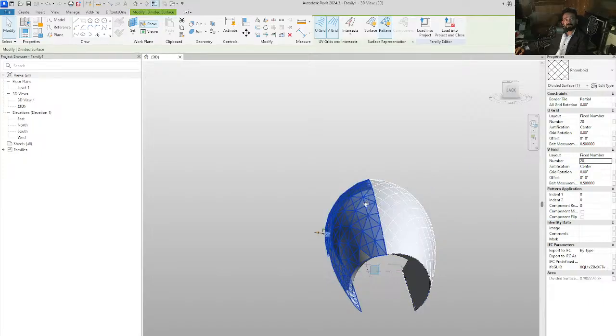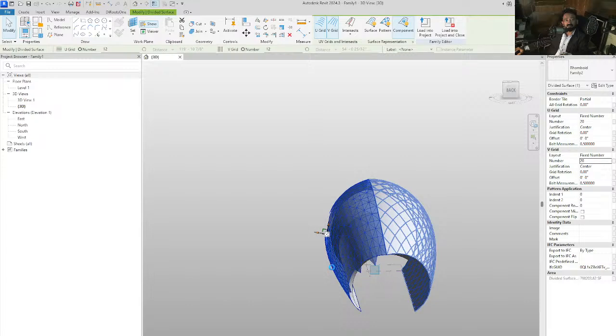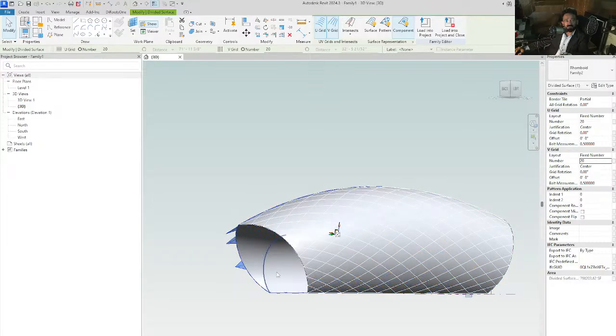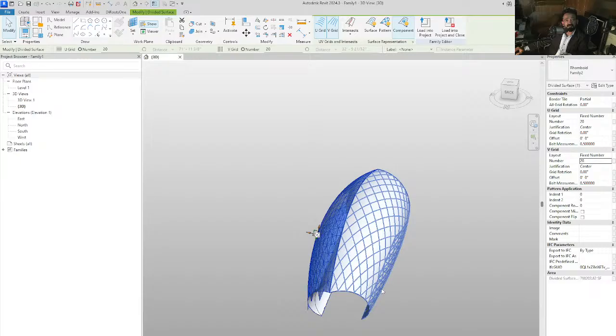So I just need to select this side and change the number from 12 to 20. But if you move these numbers too high, then Revit will actually crash. So use a reasonable number where the massing will cover the whole building. You have to wait a bit, depending on the shape, and then on this side we have our complete result. Obviously you can see some exclusions coming through.